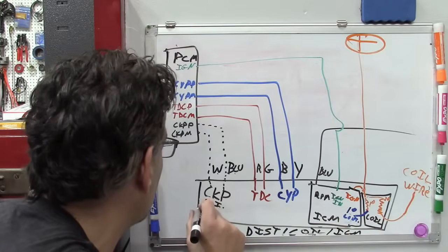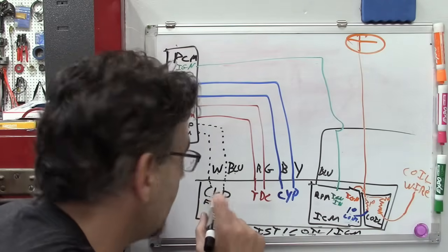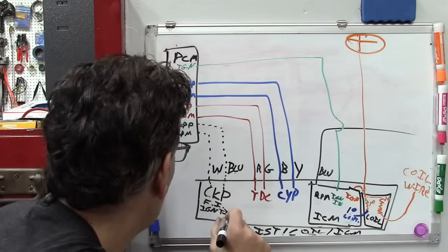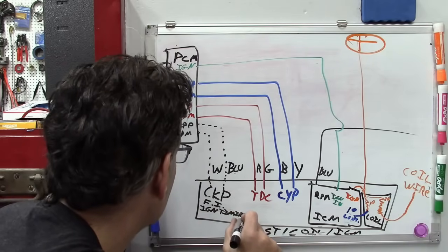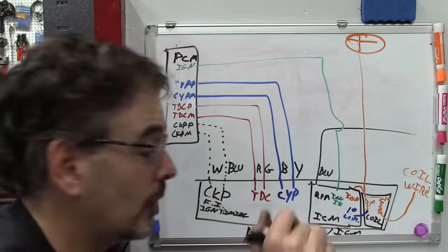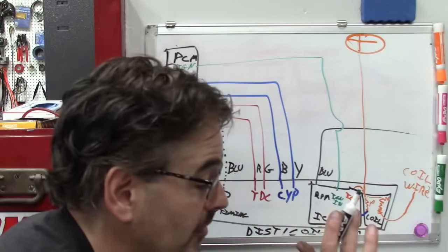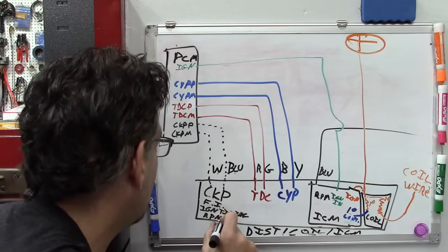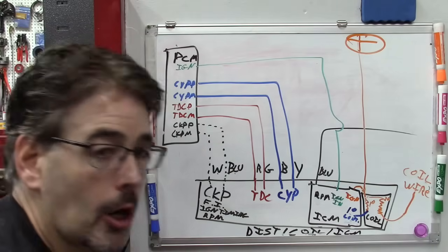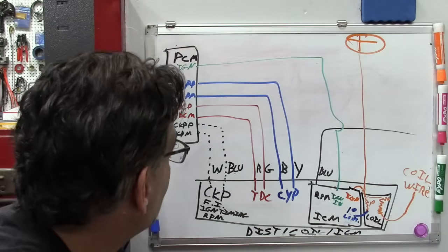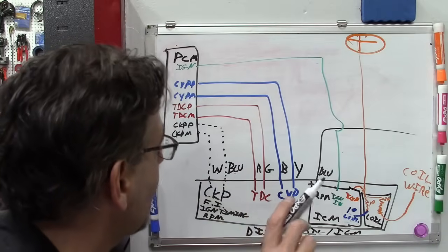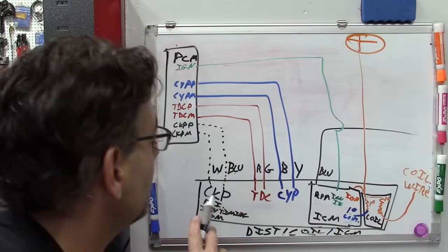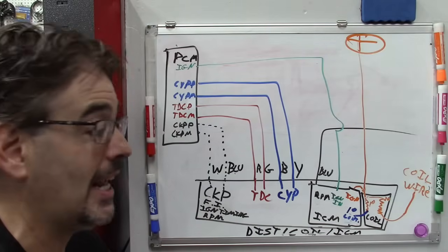It also controls the ignition timing, but while the car is running. Okay, so not during cranking, at least as far as I understand. And it also detects the RPM as well. Now, we didn't see RPM, but I believe there is a good chance, actually a really good one, that this crankshaft position sensor is not used during cranking.